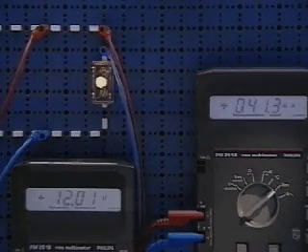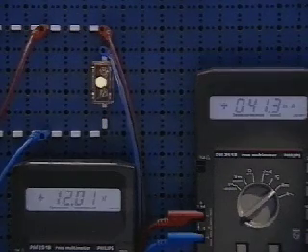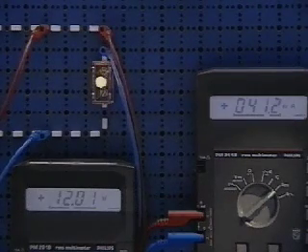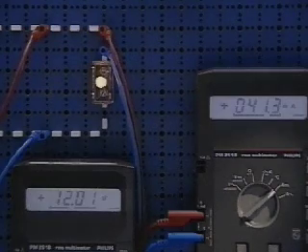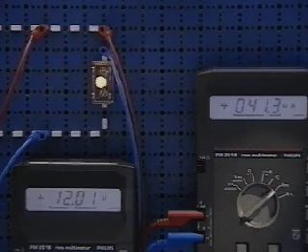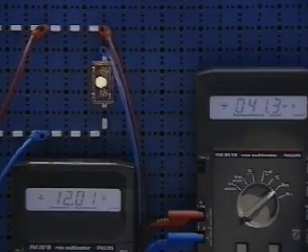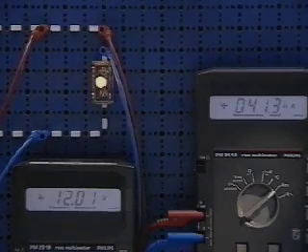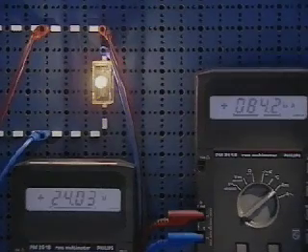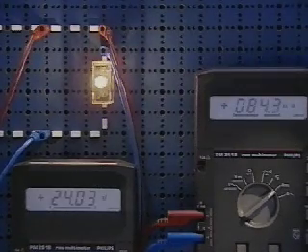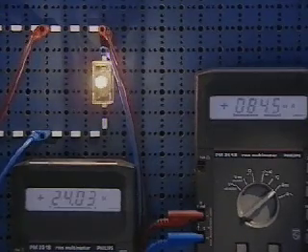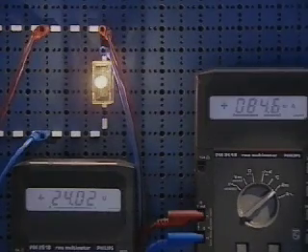But why does the lamp illuminate? And why at different levels of brightness? Here too, Ohm's law provides the answer. The filament of the lamp has a resistance which we will assume to be constant. When a voltage of 12 volts is applied, a current of 41 milliamperes flows. Because of the frictional resistance, the filament is heated by the flow of electrons to such a degree that it begins to glow. If we increase the voltage to 24 volts, the current also doubles to 84 milliamperes. In other words, twice as many electrons are forced through the filament and it gets even hotter. The lamp glows brighter.